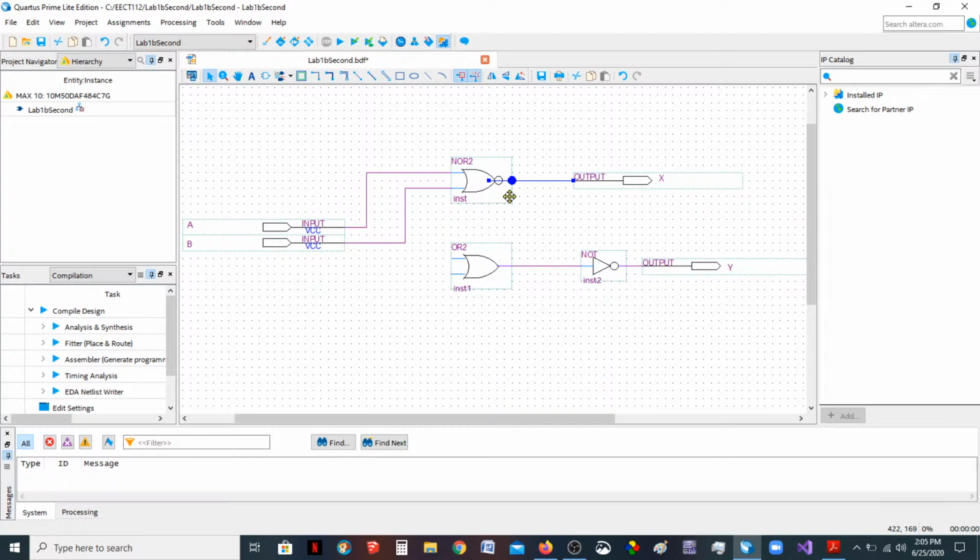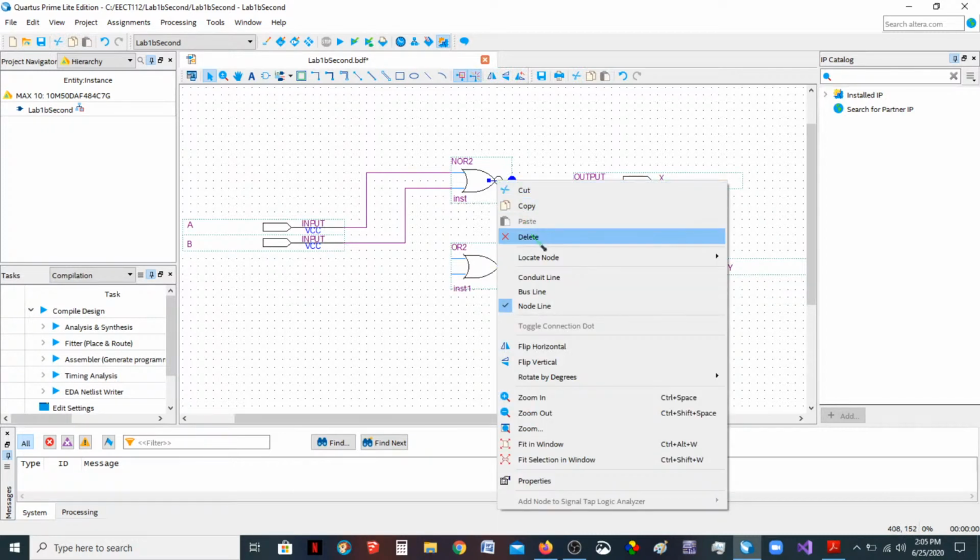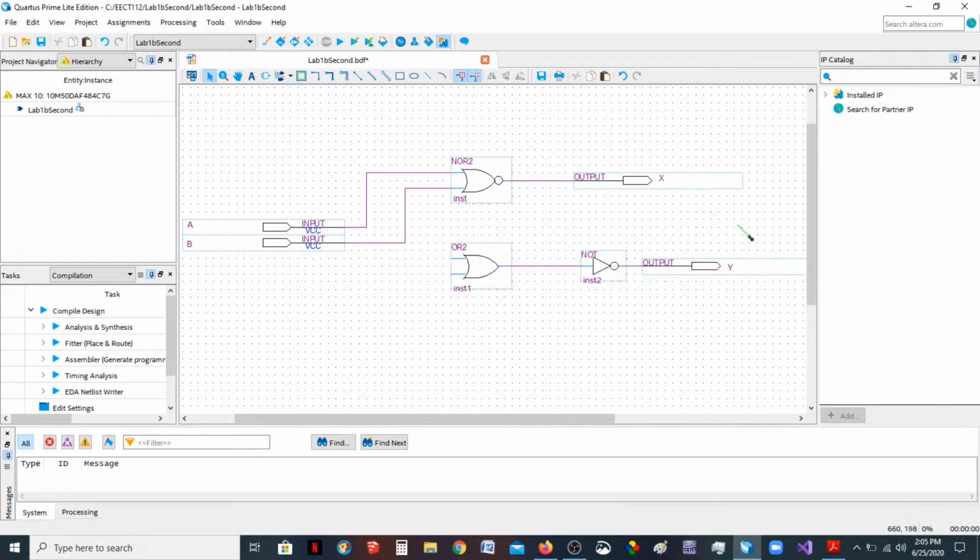So it still makes the connection here, but now I've got this dangling little piece that's underneath essentially, or it could be on top of this. I don't know, but I don't like having that there. And you see that little X. If that happens, try to select just that last little bit, and then you can right-click and delete it.